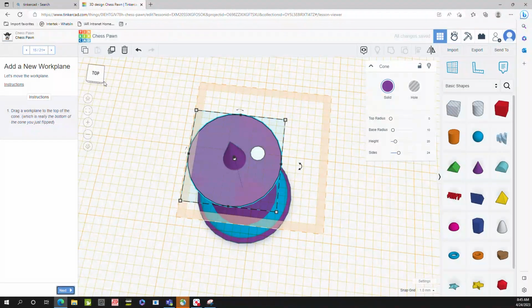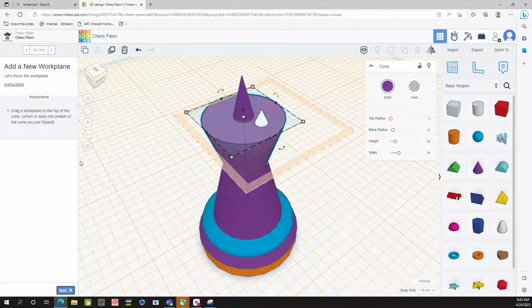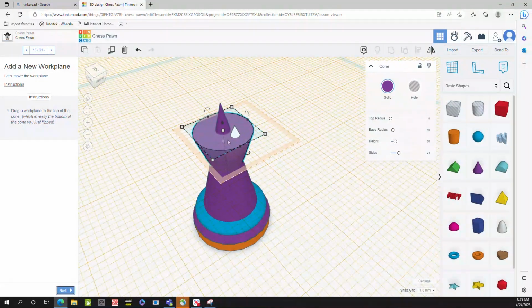and check that your plane is right. There you go. Now your plane has been moved to that place and it's pointing up. So remember that a plane has a normal, which is a perpendicular arrow telling you what direction the positive side of the plane is. That's a concept that you learn in linear algebra. For now, just know that this means that the plane is pointing up. So the X and Y are here, but Z is pointing up.